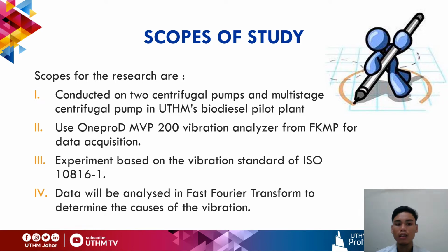The third is that this experiment is based on the vibration standard of ISO 10816-1. This standard will be explained in the literature review. The fourth is that the data will be analyzed using fast Fourier transform to determine the causes of the vibration. There are a few methods to analyze vibration. One of the most conventional ways is the fast Fourier transform method.